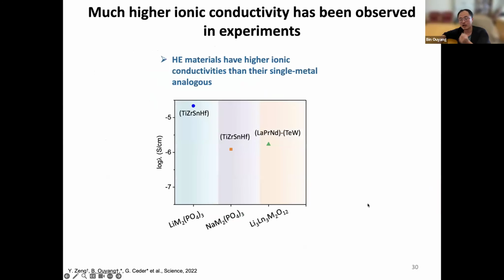And then we get experimental verifications. In experiment, we cannot just perturb the lattice. So we have to introduce the perturbation by elements. This is actually the reason why we need to go high entropy, because entropy is going to help us stabilize ions with very different ionic radii. If they have the same radius, it's actually not something we showed in the theory, right? So that's why we want to put equal molar concentrations of all the 4+, or for instance all the 3+ rare earths and all the 6+, as you see in the third column of the data. So we make those high entropy versions with equal molar ratio of each metal, and they show very reasonable ionic conductivity.